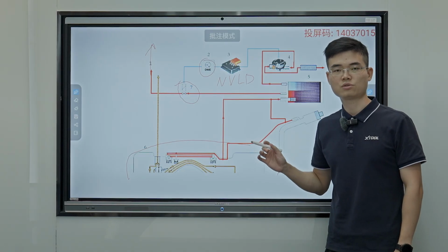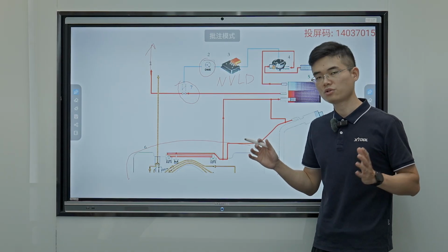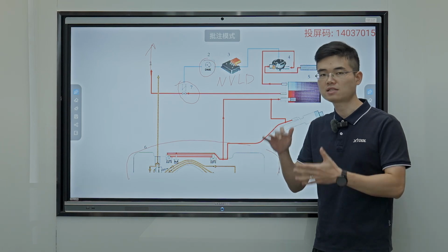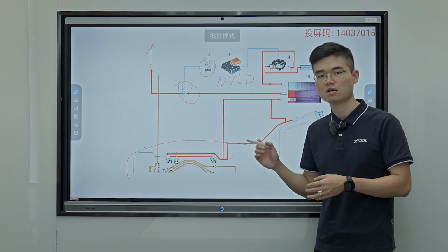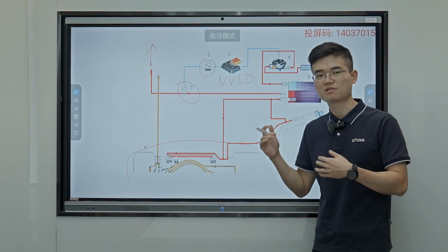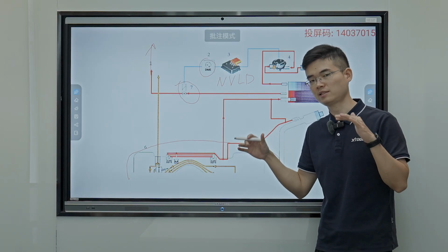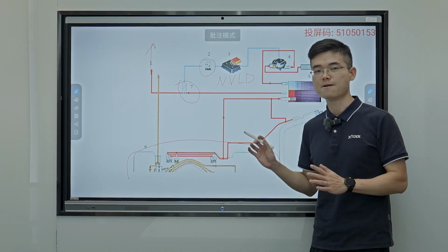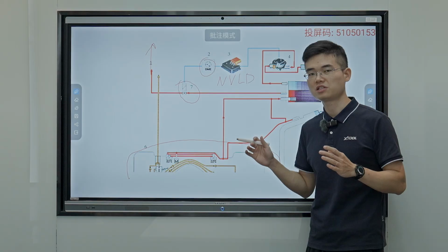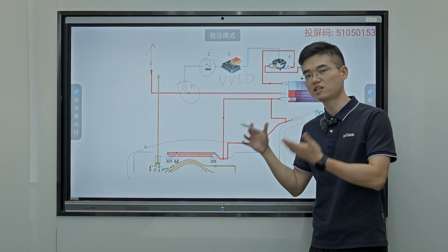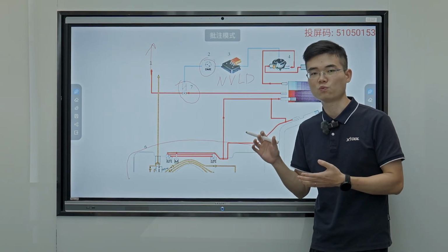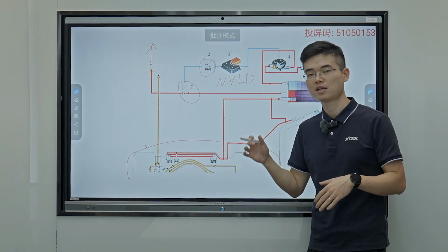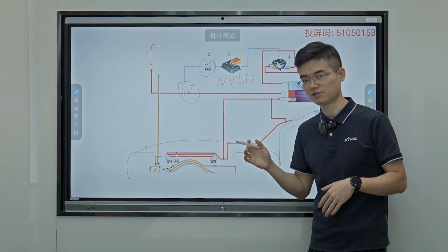Another condition is to make sure that the pressure difference between the engine being on and off should be less than 6 hectopascals. A bigger pressure difference may affect the ability to detect small leaks. And the last condition is that we do not distinguish the differences between small leakage and micro leakage. We only care about if the leakage is greater than 0.5 millimeters or not.